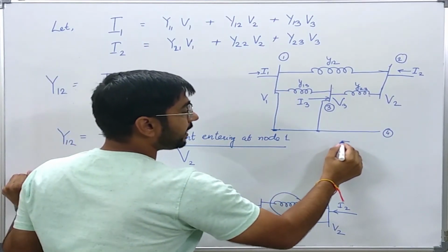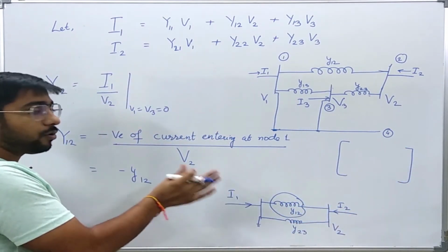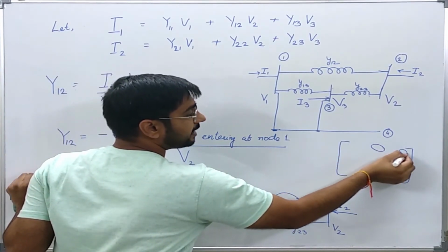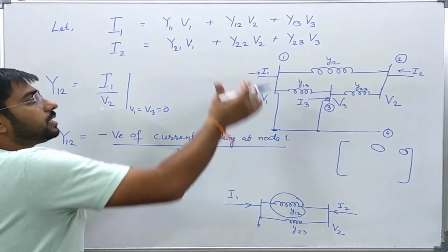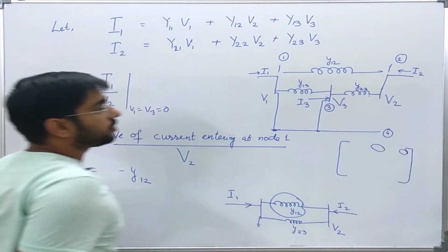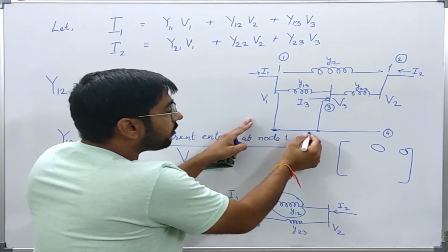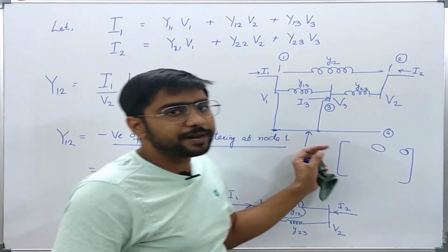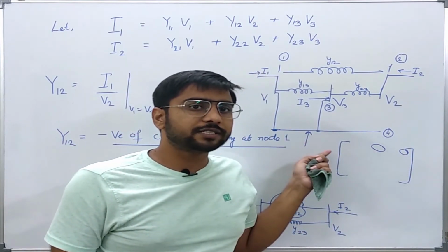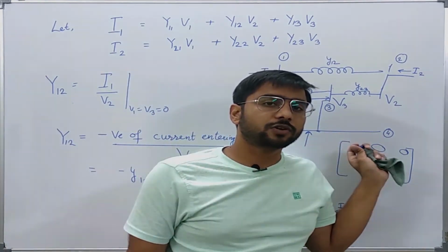So in the matrix or the given admittance matrix, we have already seen in our previous lectures that the off diagonal elements are nothing but the negative of the elements which are connected between the given two nodes. So in this way, I can draw an equivalent passive network from the bus admittance matrix. Now in the next slide, we will see whether we can do similar calculations or similar network manipulation in the bus impedance matrix or not.